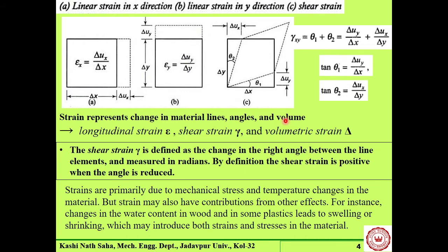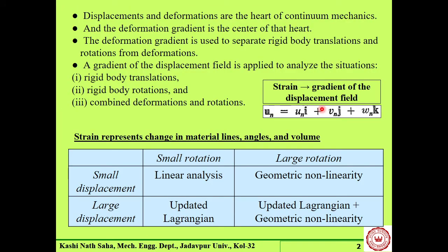Now of course you should note that this volumetric strain comes from this deformation field only. Okay, and this displacement which comes from a rigid body translation and a rigid body rotation won't change the volume. Only the deformation part will give the volume change.